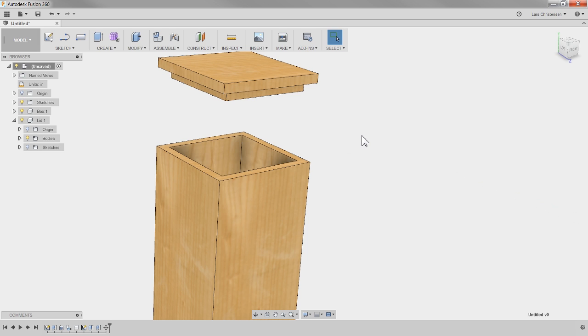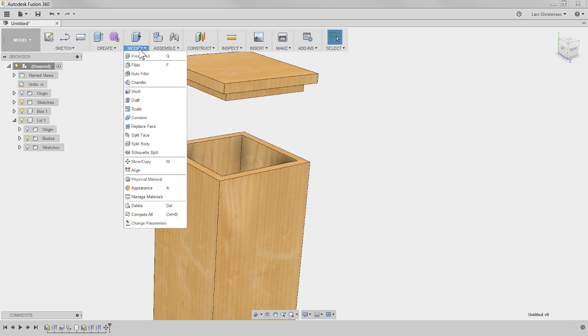There needs to be a little bit of clearance in there for it to fit together. So that's one thing we got to talk about. Now, another thing we got to talk about is that this is made out of wood, so you might use a chisel or something, but if this was made out of steel specifically, you never will do sharp internal corners. Absolutely a pain in the neck to do. We don't want to do that. So we're going to put some radiuses in there.